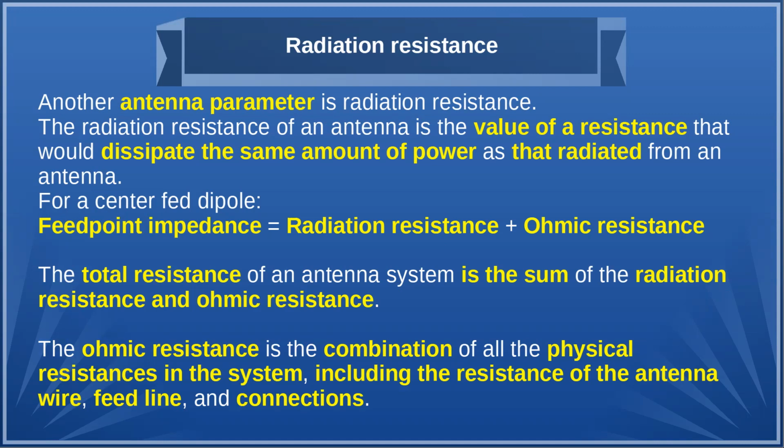It feels confusing to me because if you are talking just the antenna, you'd only worry about the ohmic resistance of the antenna. But in their definition, it's the system. So it's the feed line and everything in between, including the antenna, to get the efficiency.